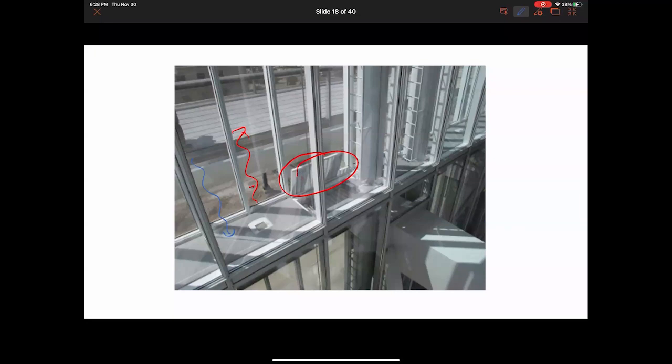But if we're relying on a passive system where there's no fan, I could totally imagine there becoming a convective loop when you have spaces that are bigger. Actually, if you have tall spaces, you get convective loops much more readily. Because there's so much separation, the heat goes to the top. There's so much more room for it to go up. And these are generally really tall spaces. So maybe that's why it doesn't.